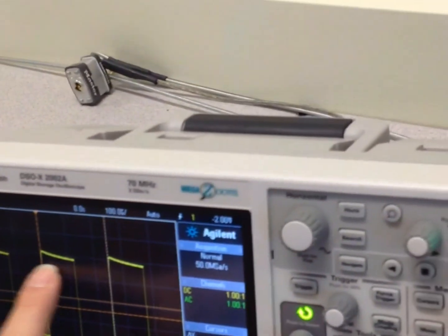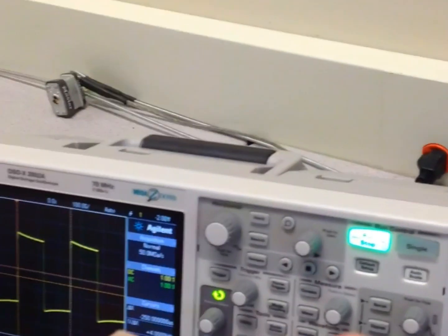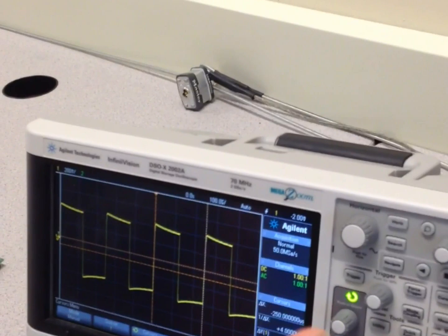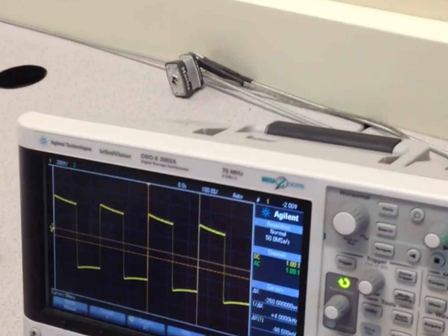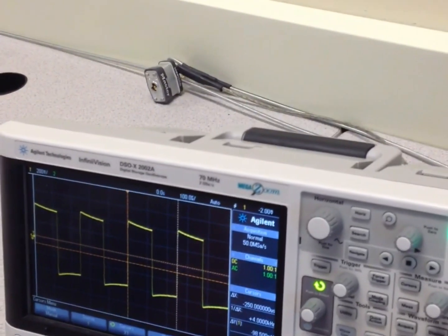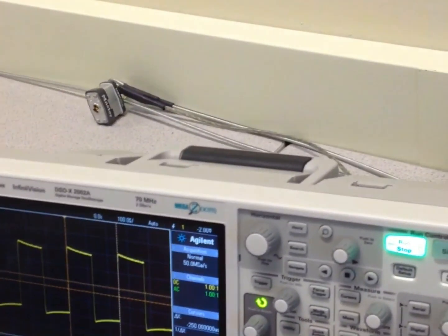This square wave, as we already know from part 1, has a Fourier series because it's periodic. It appears at 4 kilohertz, 8 kilohertz, 12, and so on till infinity. If I have a good low pass filter, I could get the 4 kilohertz only and dismiss all others. So I take the 4 kilohertz only and get a sine wave from it.